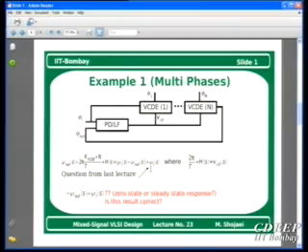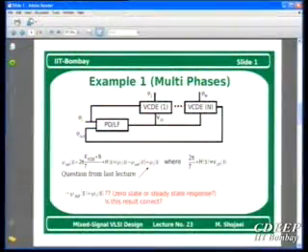Okay, so then let us write the entire transfer function. Phi out will be 2 pi upon T, K delay element into N, because we have N of them, the delay of one element multiplied by N, and then H(s), the transfer function of phase detector and loop filter, times phi I minus phi out plus phi I. And this 2 pi upon T H(s) essentially gives us VCTL.